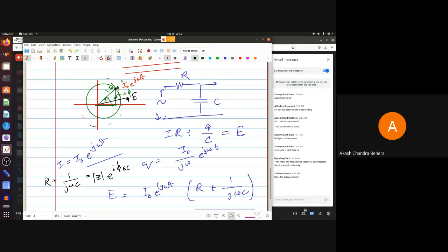Sir, when the current phasor is on the real line. When it's just on the horizontal axis, right? When it's just crossing the real line, right? That's when this projection is the largest. When it just crosses the real line again on the other side, you get a minimum. And when it just crosses the vertical axis, although my picture doesn't really show it properly because it's off center, there you get zero projection, right? That is, then the current will be going through zero.